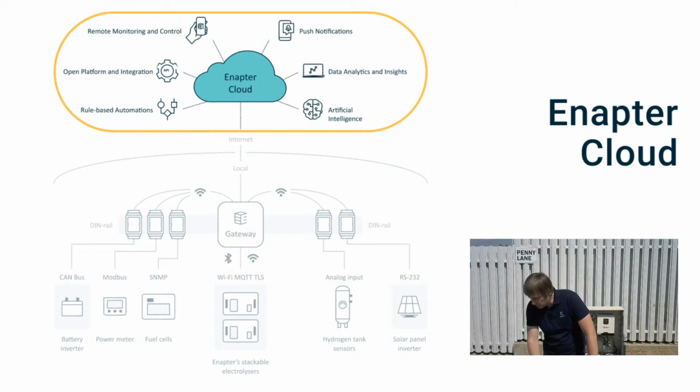The question from Giorgio: sorry, I lost partly your explanation. What is the flexibility to accept other devices by Modbus RS-232, for example, a board of other appliances in the heating room? Okay, so what you need to do is take our RS-232 module with a Lua SDK. Then you just scan the QR code of this module, and it is connected to the cloud.